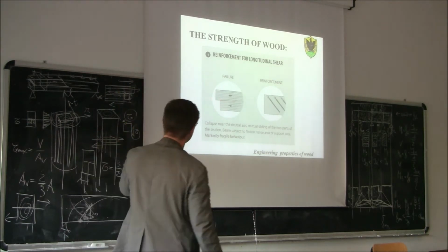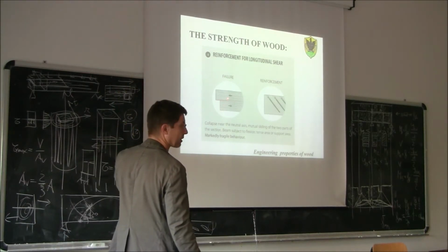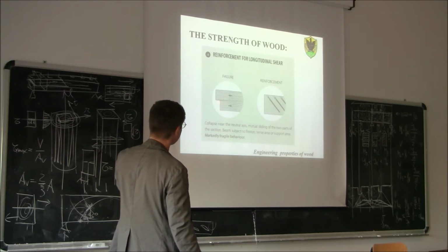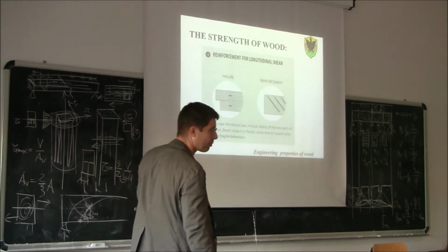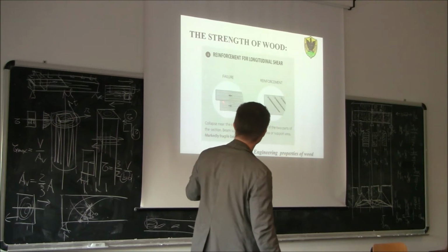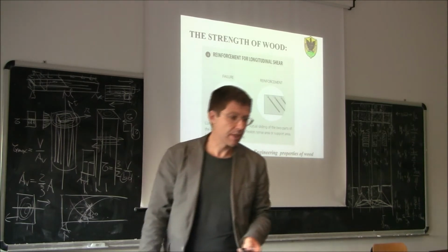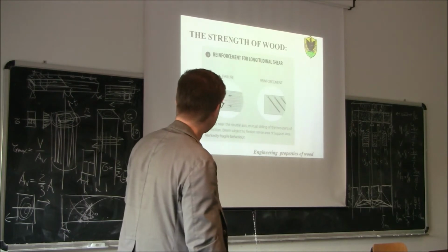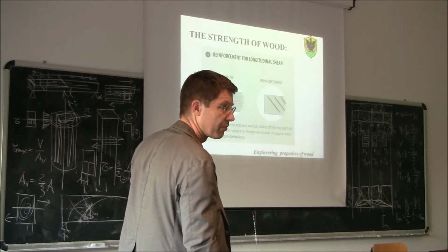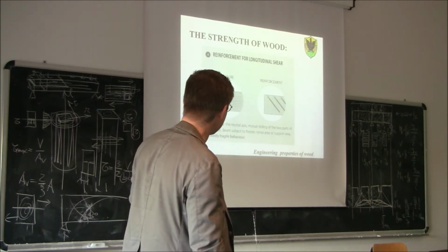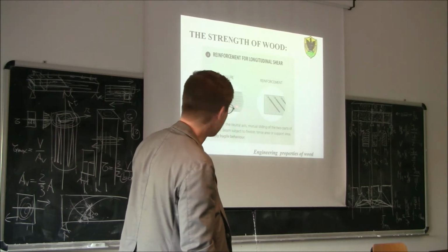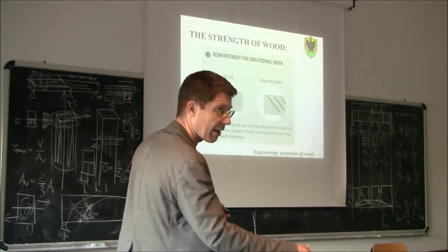Remember also that if you have a notch like in this case, this point here is a very delicate point, because when you have a corner like this, you have a stress concentration, and very often you have a crack formation here. So the best thing would be never to cut a notch, but if you cut a notch, you can expect a crack.